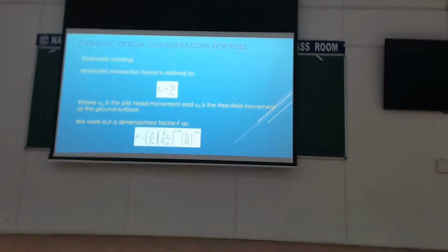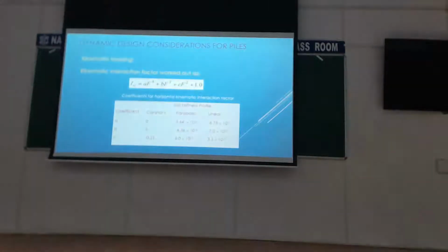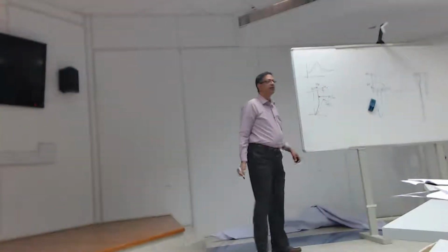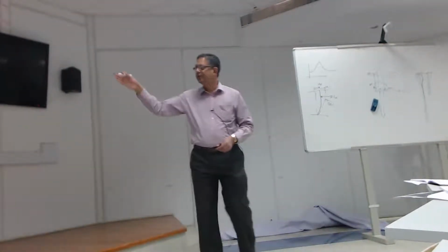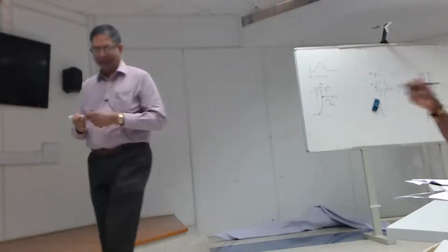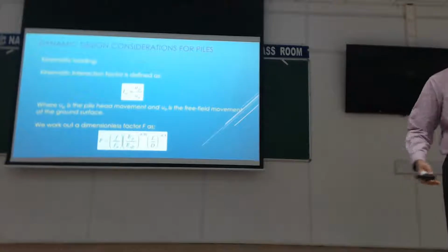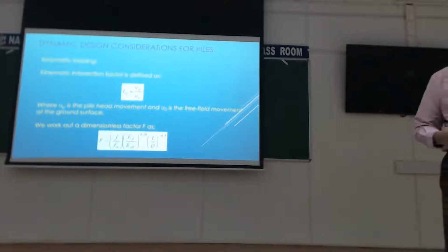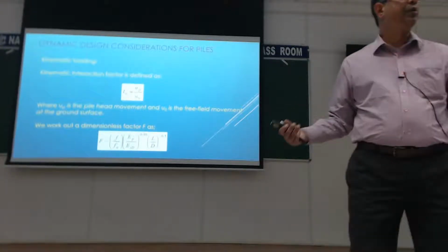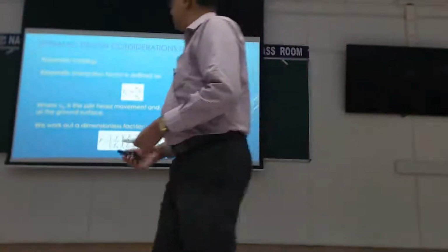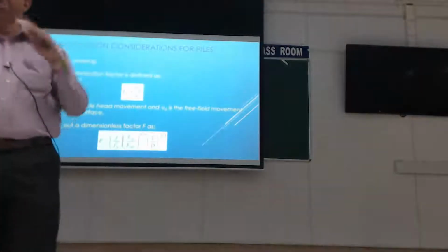If my F is far away from the natural frequency, then this ratio will be small. So we are basically trying to get a response curve looking something like that. That function will do that for you. So it's like incorporating the resonance into the equation. Everybody happy with that?